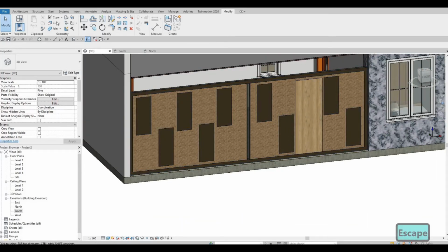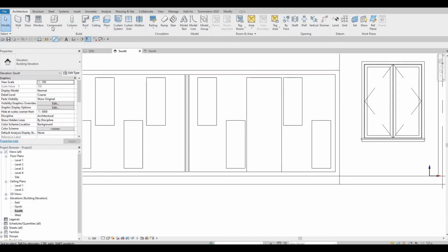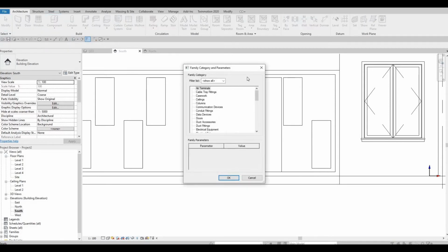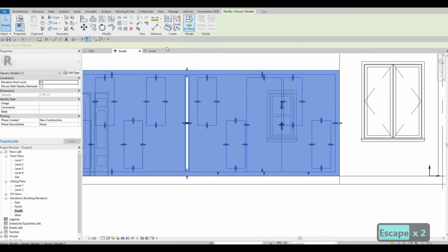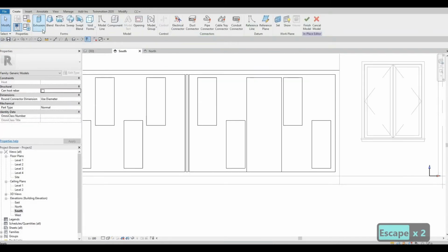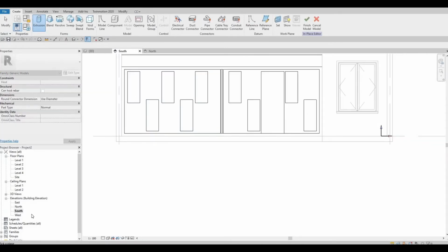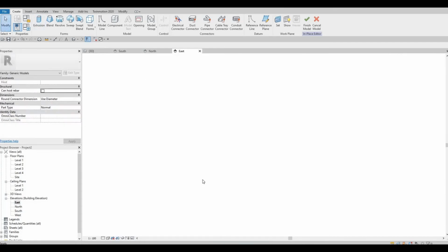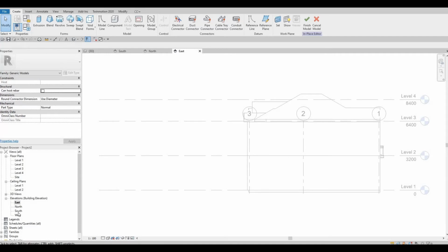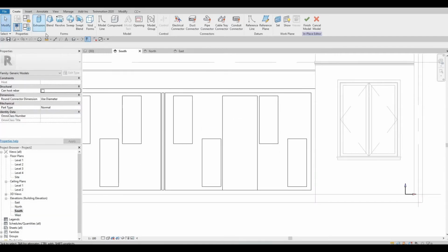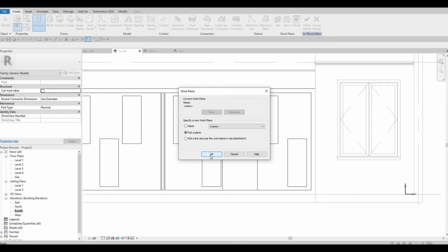And then here, let's just add in another model in place just to add a doorknob there. So I think we could just use an extrusion. Let's use the front and then regular extrusion.